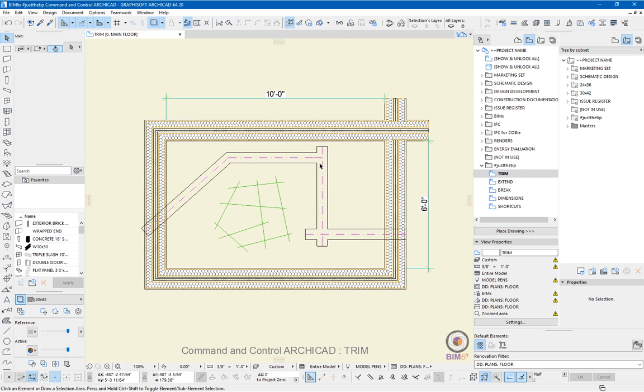So in this case it's trimming away there. If I control click in the middle, then you'll see it trims to the two nearest points. So in terms of these lines, I could either trim away the middle pieces, or we could come in and tidy up these ends. Literally all I'm doing is holding down the control key and clicking to trim away.